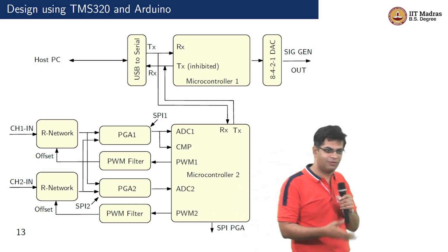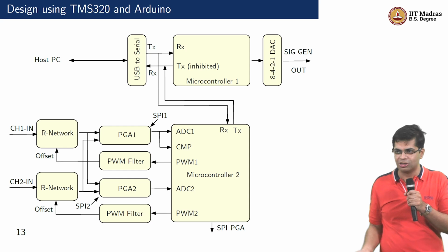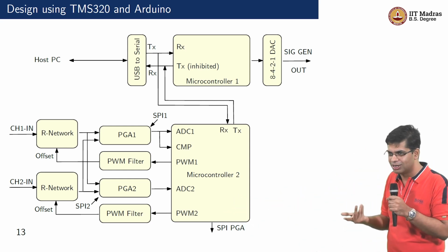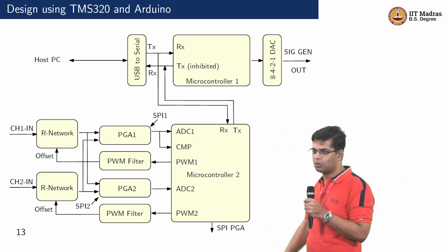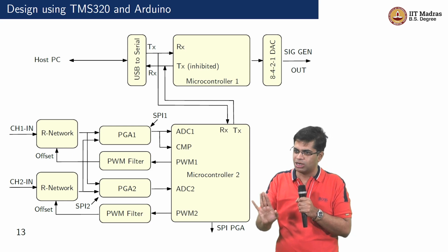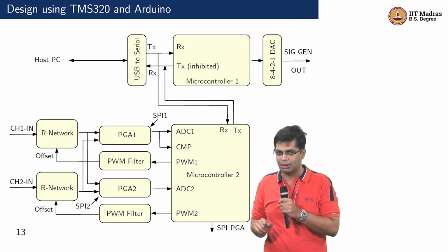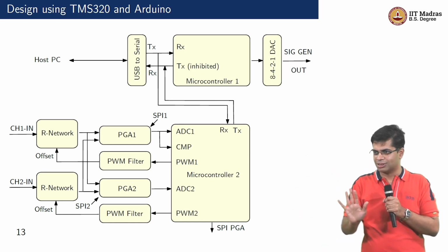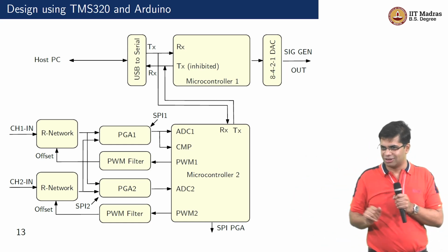Okay, so we had this thing. We bought 200 Arduinos and we found that in our previous slot it is working, this slot it is not working. Then we had to spend time to actually debug what was the problem. We went into the Arduino board and changed a few resistors. That's all it needed finally. But debugging that took time. Instead of 10K, we made it 100K. It works. But too much effort, right?